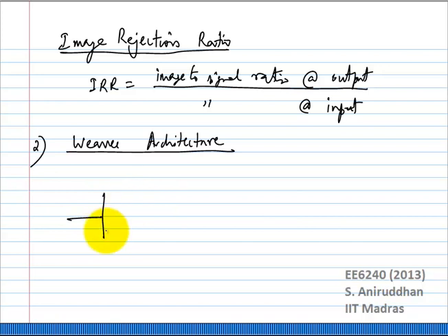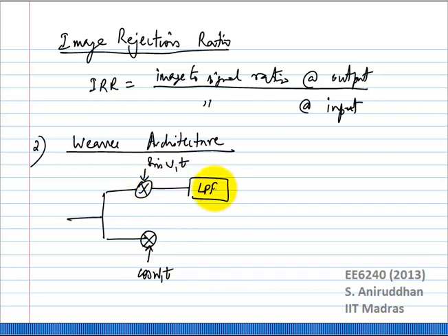So you take your RF input, so you go through one round of mixing, okay. So the first round of mixing, you mix with sin omega 1t and cos omega 1t. Now instead of actually adding a phase shift, okay, you can do a second round of mixing.